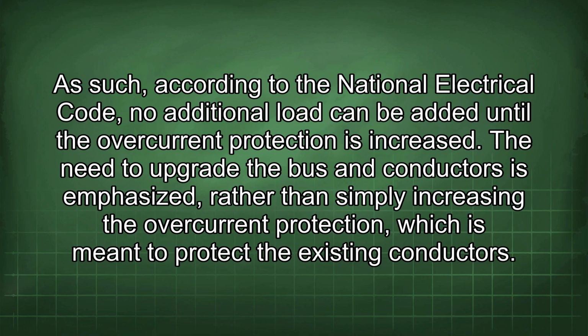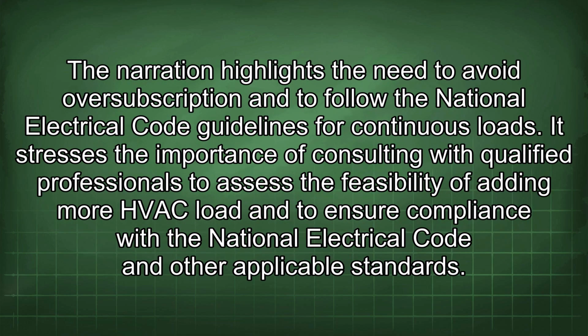As such, according to the National Electrical Code, no additional load can be added until the overcurrent protection is increased. The need to upgrade the bus and conductors is emphasized, rather than simply increasing the overcurrent protection, which is meant to protect the existing conductors. The narration highlights the need to avoid oversubscription and to follow the National Electrical Code guidelines for continuous loads.